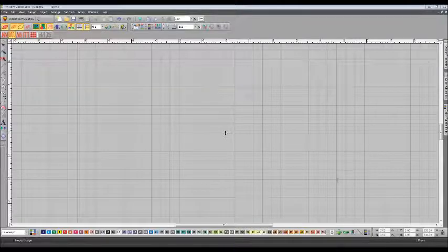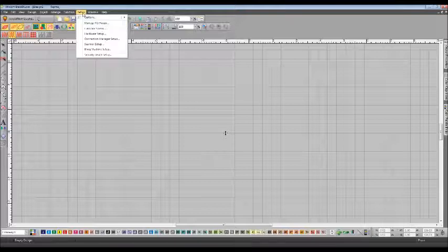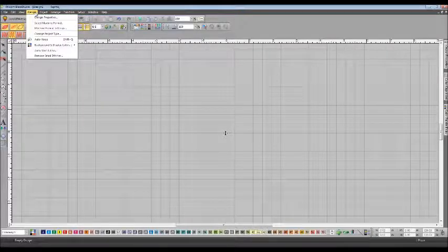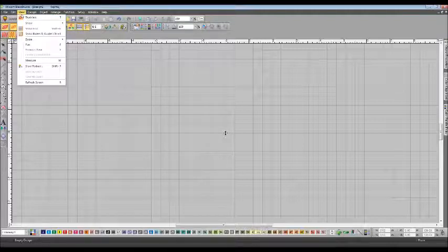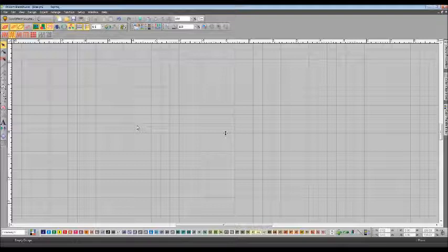So if you have a box, a circle, and a triangle, separate objects, and they are overlapping, will DecoStudio delete the stitches? Let's try that. There's something in here called remove overlaps, and I'm not sure if DecoStudio has that option, but there will be a way. In fact, I don't see it in here, but there is a way to do it manually, and I'll show you using the knife tool.